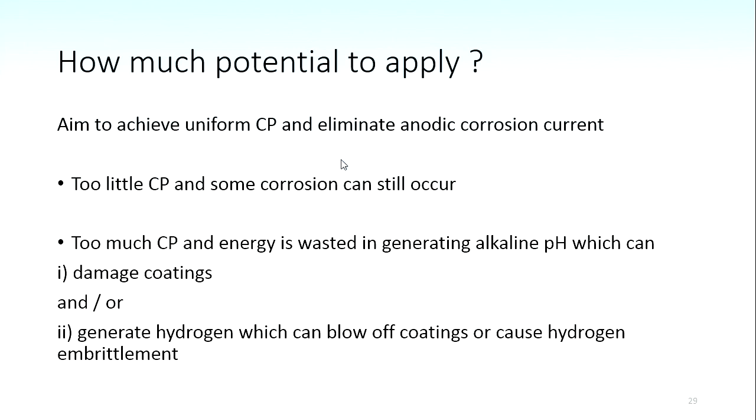Basically, the difference between these two electrodes is 50 millivolts. It's 48 actually, but it's 50 millivolts. So when you've got minus 800 to minus 900 copper-copper sulfate, which is giving you some protection, that's minus 750 to minus 850 in the silver-silver chloride seawater electrode. So it's 50 millivolts out on the shift for the zone of protection when you're using the other reference electrode.